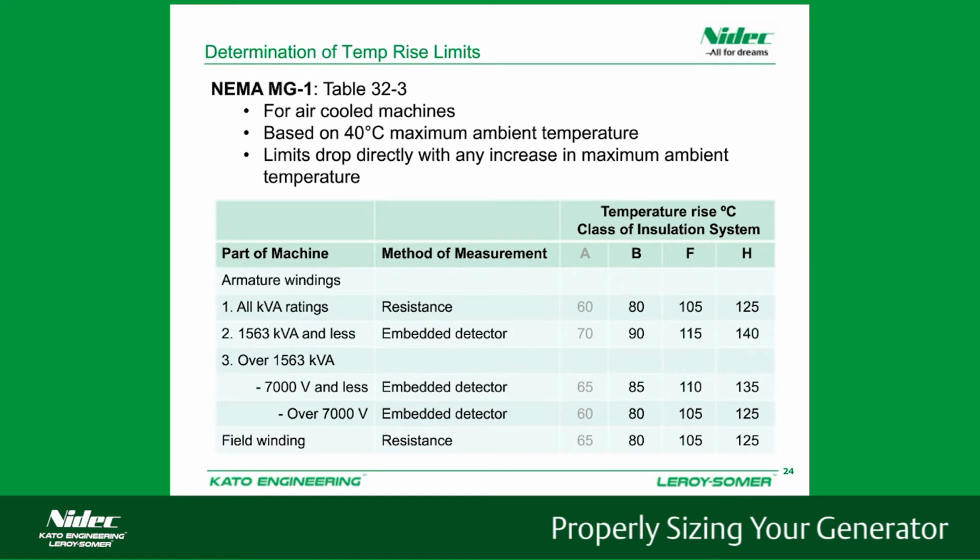And our field winding, our rotor, we typically don't put RTDs in. I don't know if we can or if anybody does. It's hard to measure them when you have your field spinning. But those are, again, allowed to 80, 105, and 125 degrees.